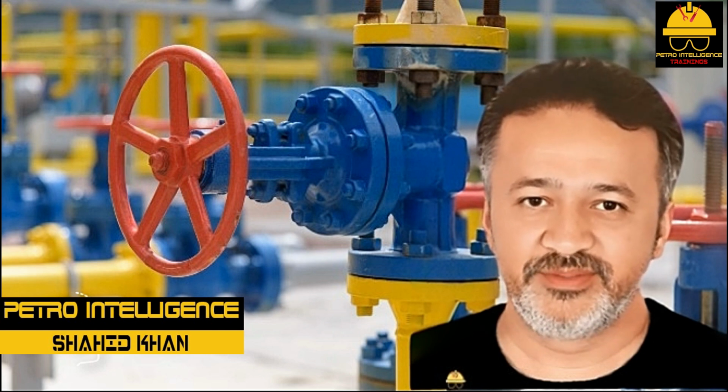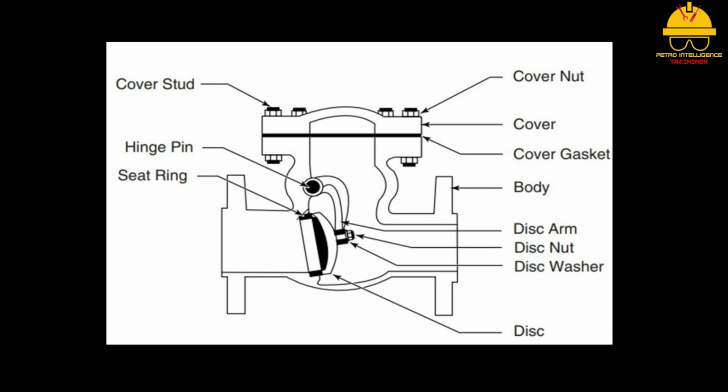A typical check valve design is the swing check, which has a hinge disc that slams shut when flow reverses as shown in picture. Flow lifts the disc and keeps it lifted until flow stops or reverses. The body of the check valve has a cap for easy access to the flow control element.